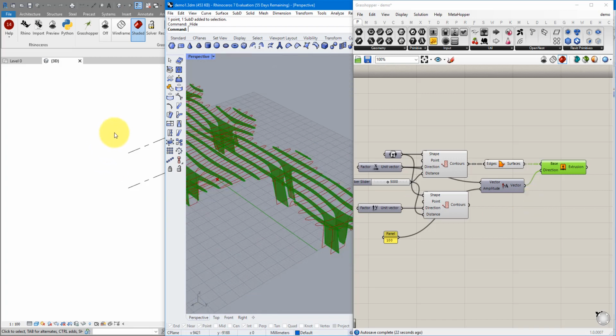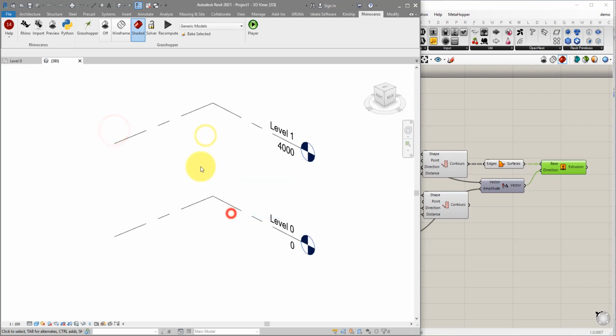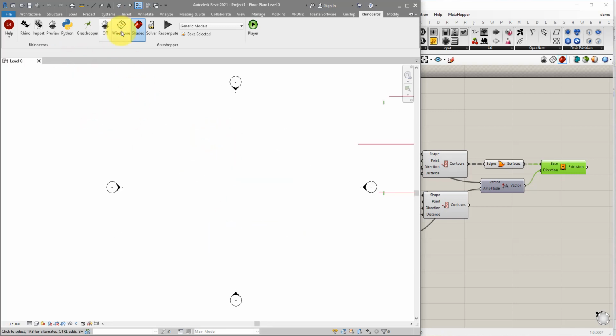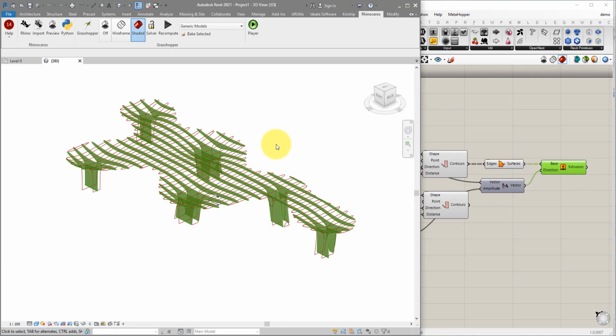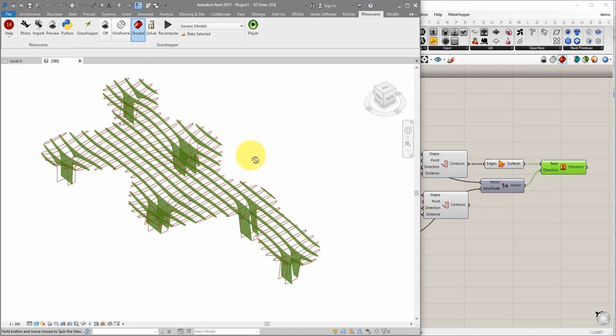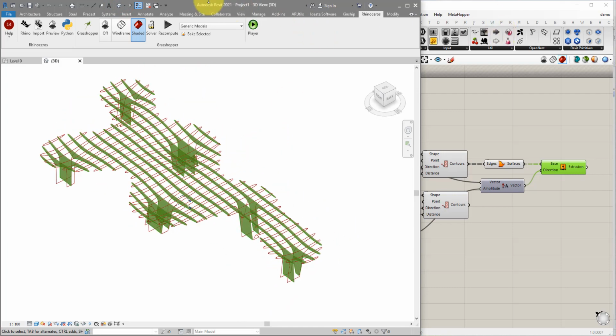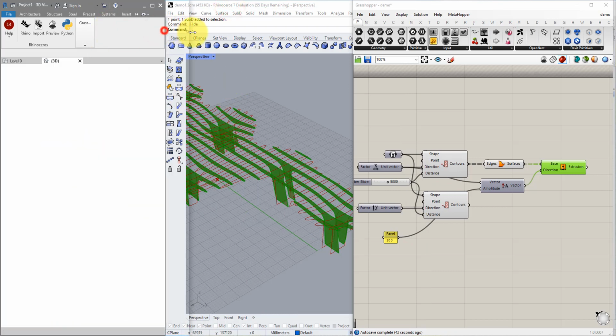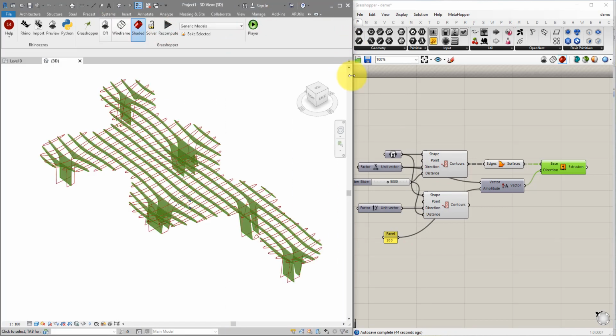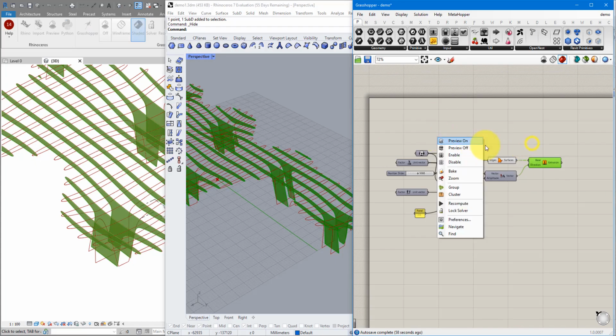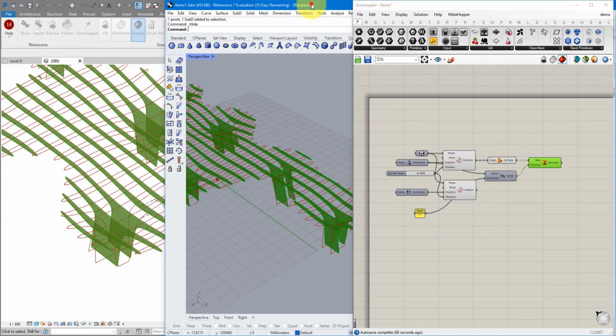Now I'm wondering if there's a preview in Revit already. We may have to reopen the view. Yes, here they are. From this point onwards, we can just work with Revit and Grasshopper. Rhino is still there in the background, because that's where the Surface form is coming from. But in terms of creating structural members, we only need these two windows for now. So, to bring these frames into Revit, let me actually close Rhino so it won't get in the way.